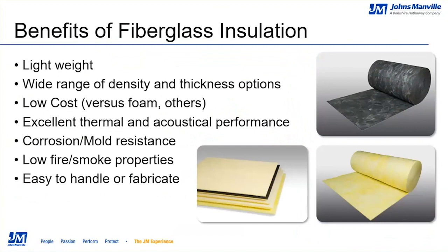In addition to the thermal performance benefits of fiberglass, these materials are excellent sound absorbers. They are among the most widely used acoustical materials in a wide range of applications. Fiberglass products are lightweight, which makes them easy to handle on the job site, and they come in a wide range of density and thickness options. They can also be very economical versus other products such as foam materials. They provide excellent corrosion and mold resistance, as well as low fire and smoke properties. Finally, products utilizing fiberglass materials are easy to fabricate and handle for the installer.